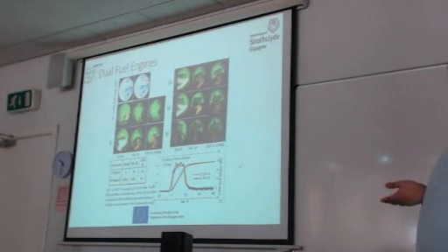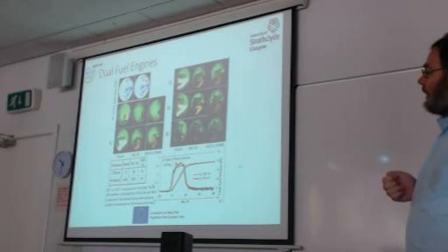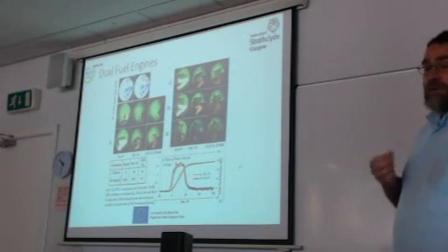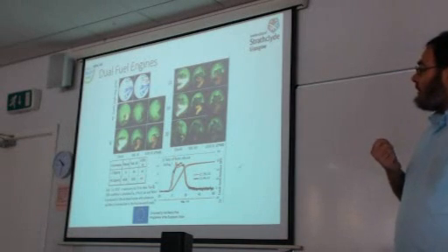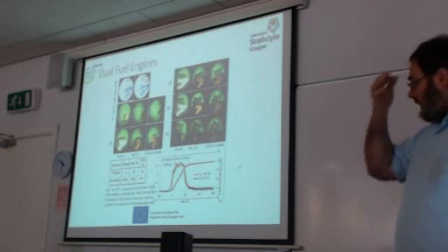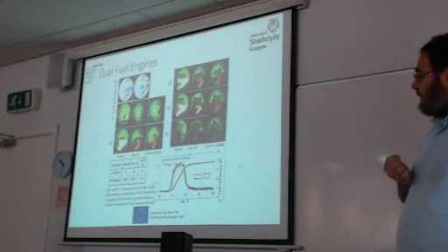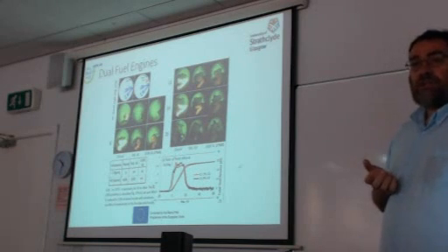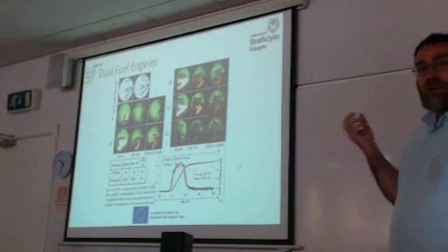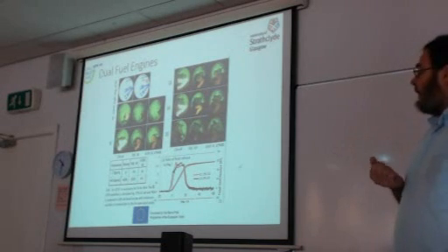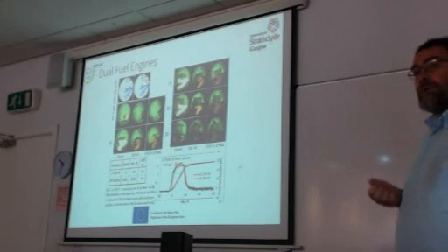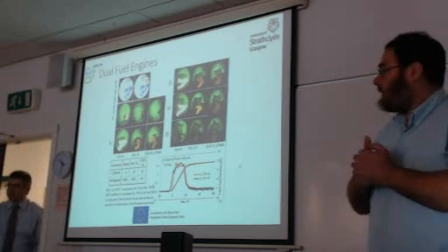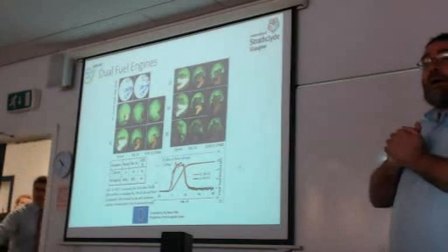Which are the advantages, which are the disadvantages of this engine? So the advantages are that the gas can replace perfectly the liquid fuel. There's no need for installing another cylinder. The engine produces the rated power, even in dual fuel mode. The disadvantages include the NOx limit, the NOx emissions, which are high. Of course, they are reduced relative to the diesel mode, but are still high. So I think the reductions are about 40%. But if you remember from my first slides, an 85 or 90% reduction is required.